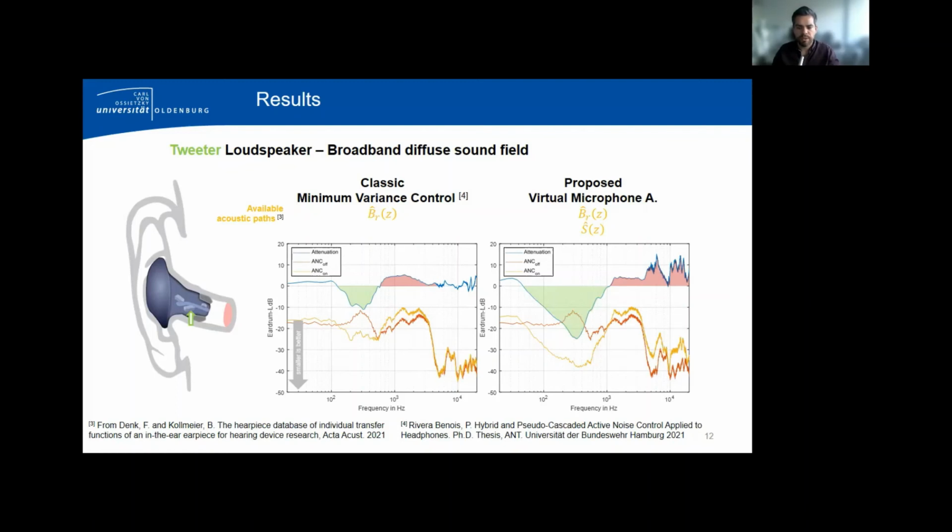By comparing both attenuation curves, it is visually clear that the proposed optimization procedure achieves an attenuation that is approximately 12 dBs higher when compared to the classic optimization procedure. Moreover, an increment of attenuation bandwidth of approximately 550 Hz is achieved. This amplification produced by the waterbed effect in the mid frequencies remains under the specified maximum amplification of 4 dBs, until the 4 kHz frequency is reached. The uncontrolled amplification that occurs for frequencies higher than 4 kHz is produced in a frequency region where the closed earpiece already provides sufficient passive attenuation.